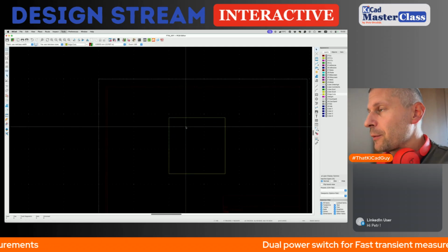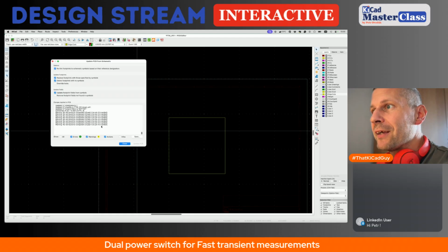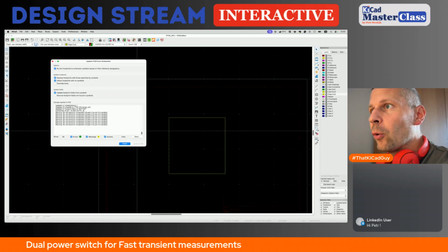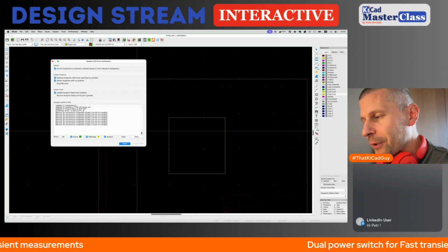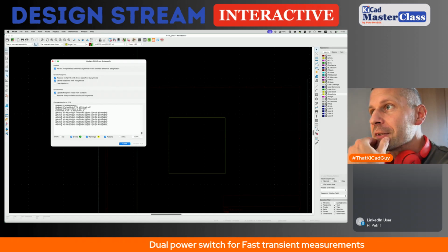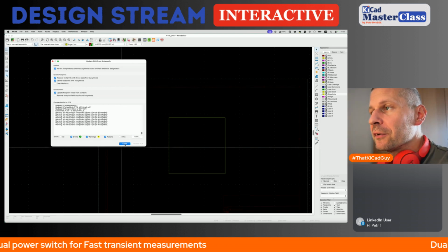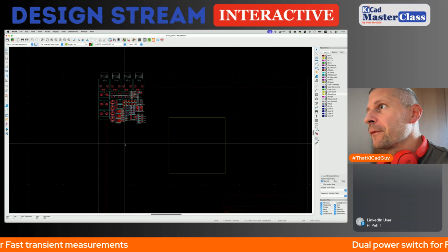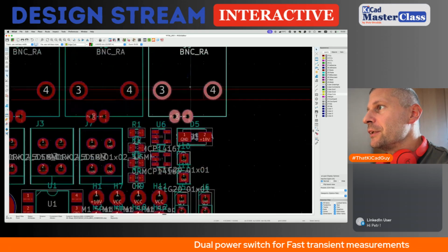Okay, so let's update the PCB to see what's the situation here. We have 8 warnings. No net found for J9 pad 4, pad 9, pad 4 and pad 3, and this is 4 times repeated. So let's check the J9. What is J9? J9 is BNC.